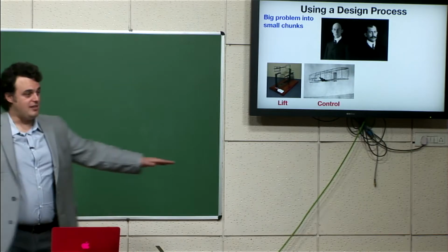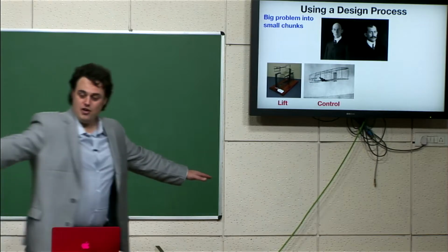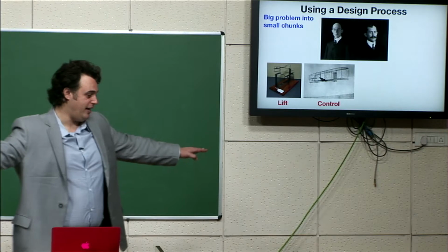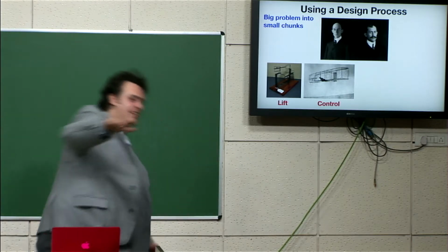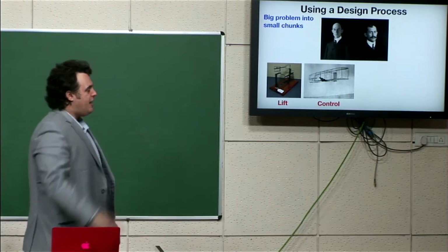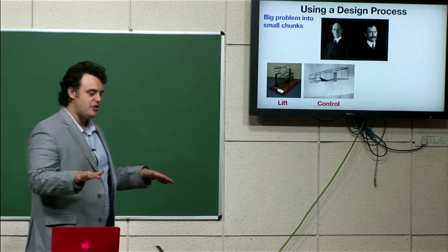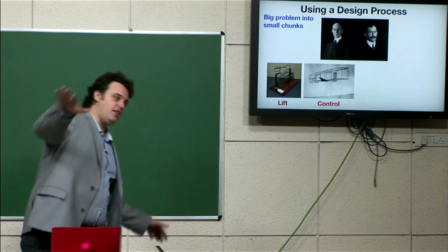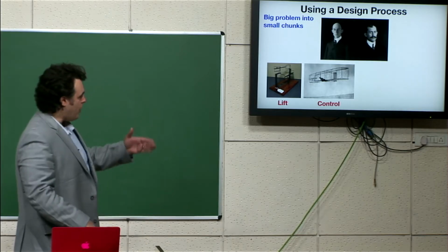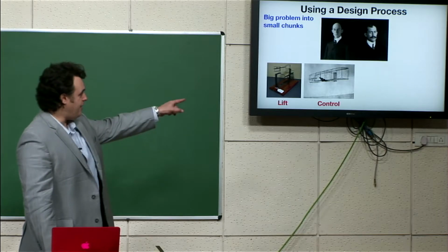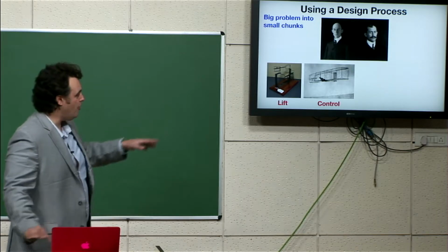The problem is, as you make a turn, your outside wing gains airspeed and lift, your inside wing loses it, and you can crash. That's why you have to do a bank turn. And so they developed a wing warping system, which was a kind of rudimentary means of ailerons to tilt the plane, as well as rudders, as well as elevators, and they mastered control, right? That plane had 3 degrees of freedom of control.